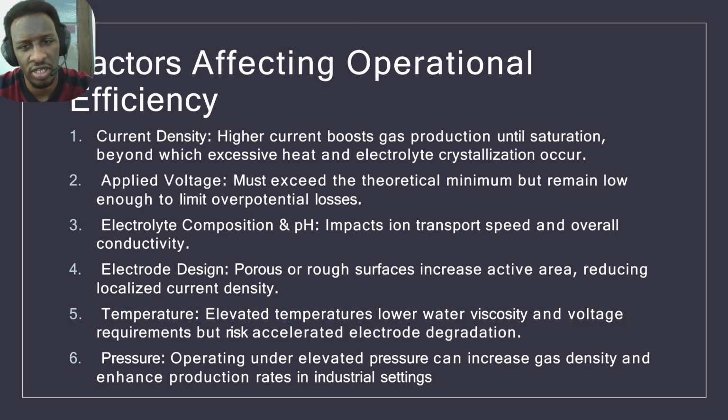Now, the factors affecting operational efficiency of this technology. First of all, current density. Higher current boosts gas production until saturation, beyond which excessive heat and electrolyte crystallization occur.